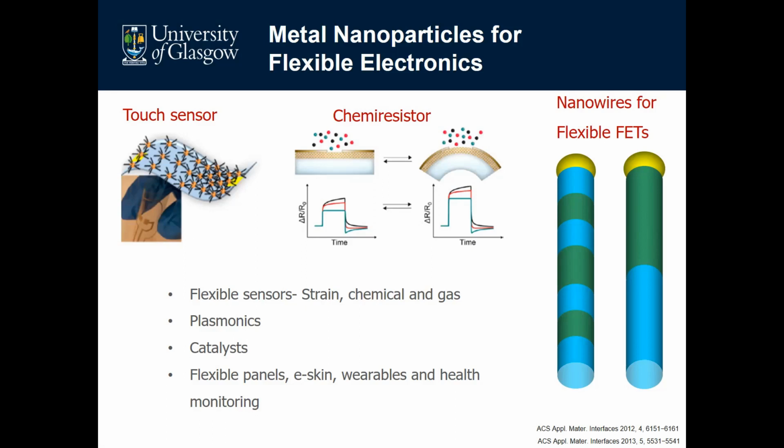Or if you're using a flexible chemiresistor, which is needed to sense gaseous species of harmful, toxic or flammable gases in the order of sub parts per million scale, these could be detected using metal nanoparticles. For example, if the functionalized metal nanoparticles are deposited on a substrate, a small strain variation in the structure could lead to a significant change in conductivity. This change in resistivity could be directly correlated with the gas absorbed over the functionalized metal nanoparticles.